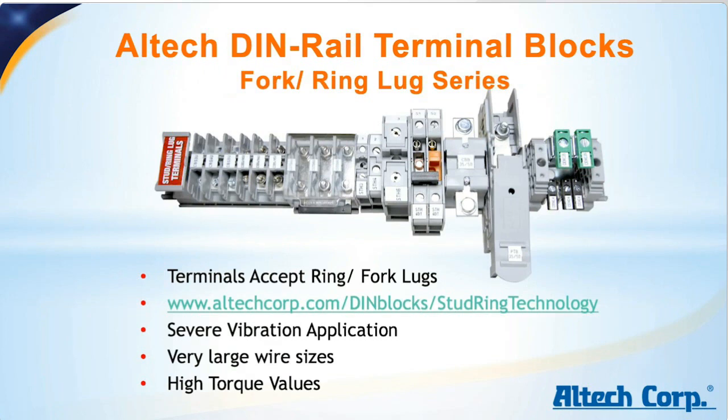A special form of screw terminals are stud terminal blocks. These terminals accept fork and ring lugs. There's many different designs available. Some are open type, some have protective covers. And it's especially high current systems which also see a lot of vibration that utilize these terminals, some of which have current ratings up to 500 amps.